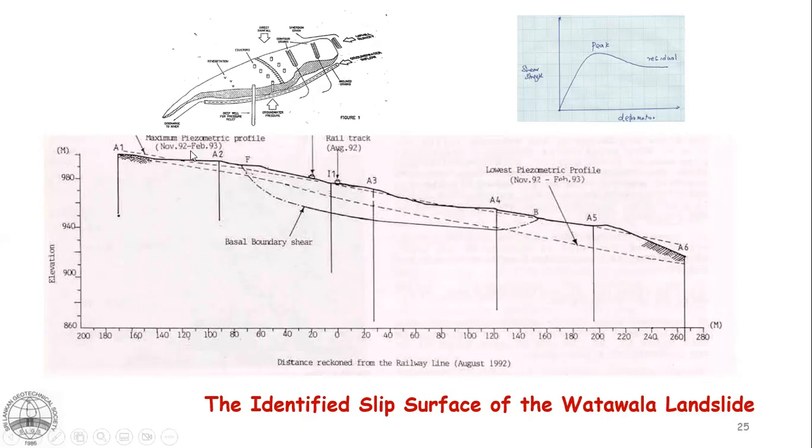So the critical target area is this failure surface. The movements are happening along this failure surface. You have to provide rapid dissipation of pore pressure, prevent the rise of the water table from here to here, and ensure dissipation of pore pressure closer to this identified shear surface.